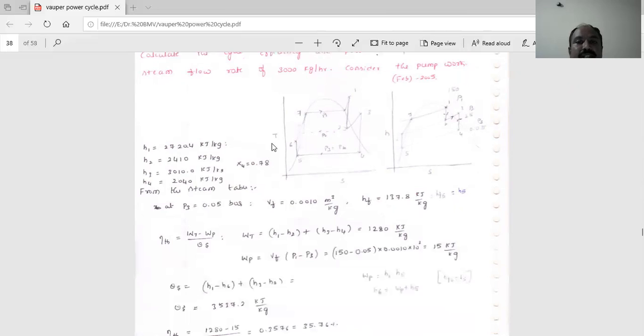Here the reheat cycle is there, so that's why we have to write down that reheat cycle TS and HS diagram. Here 1 to 2, that is condensed heat, it becomes a liquid wet steam. Okay, 1 to 2 it becomes within that curve. You should write it like that only, within that curve. Then we have to write down from the Mollier chart the values of H1, H2